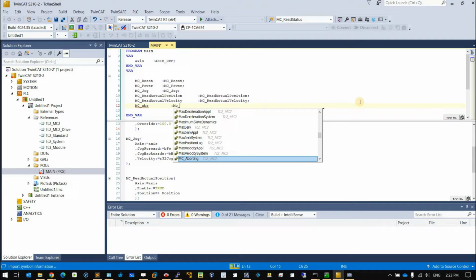If you're using relative positioning, it depends on your current position, then you plus or minus the distance. For example, your position is now 100. If you use relative positioning with a distance of 200, after you execute the function block without any error, your position will be 100 plus 200, equal to 300, and the second time will be 500 and 700 and so on.